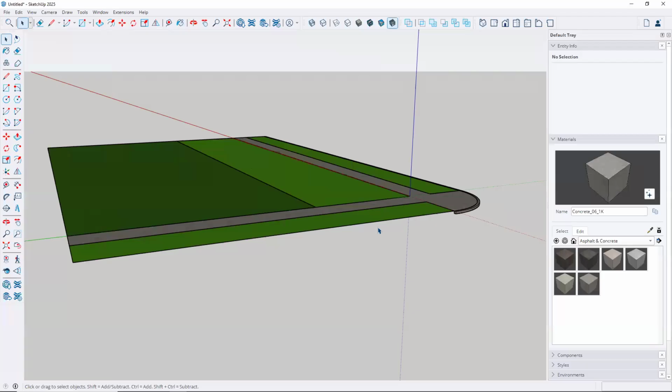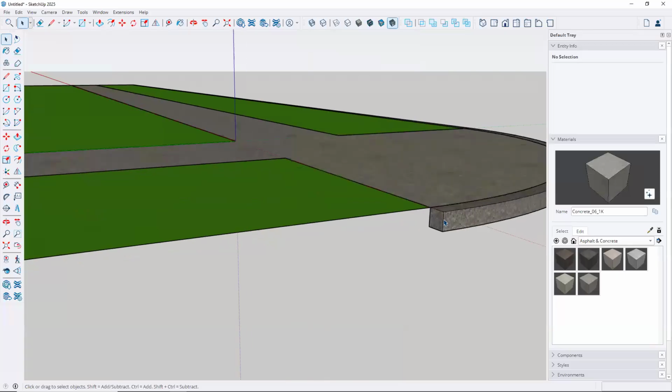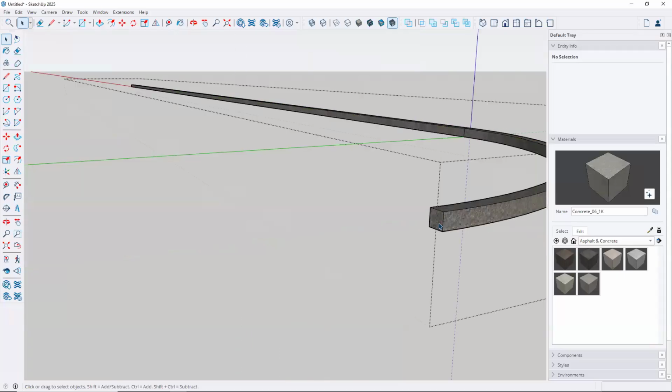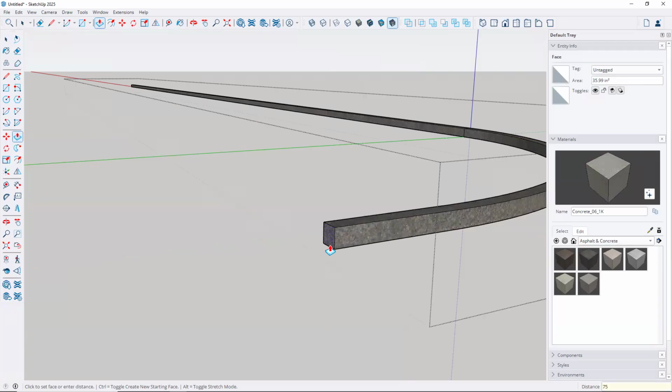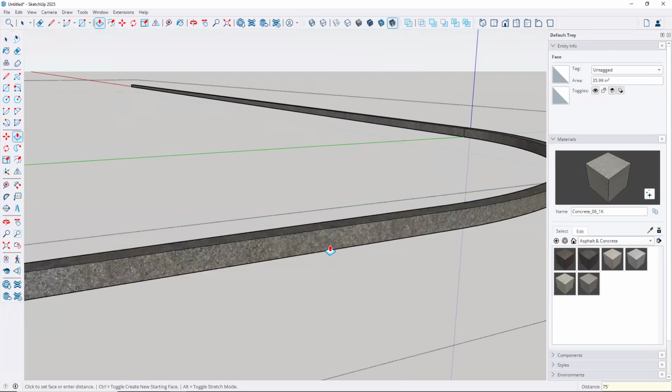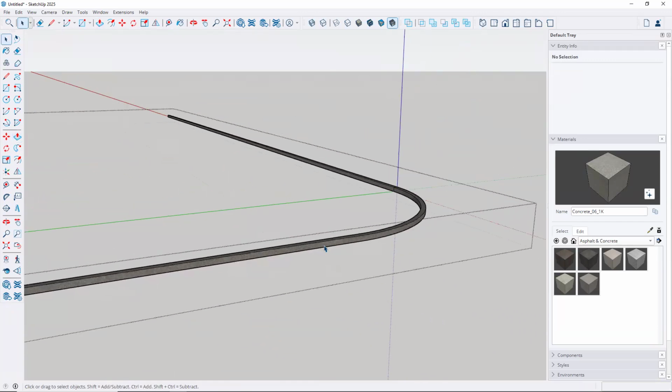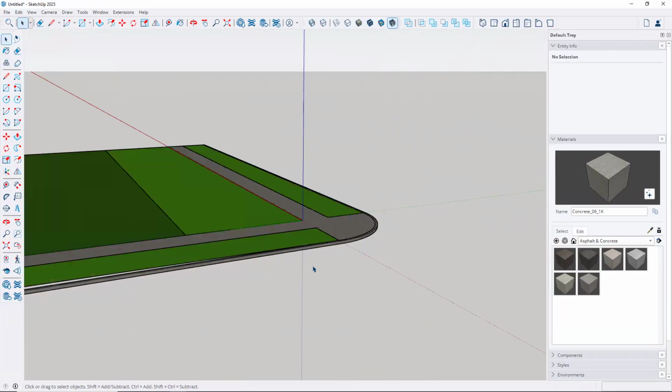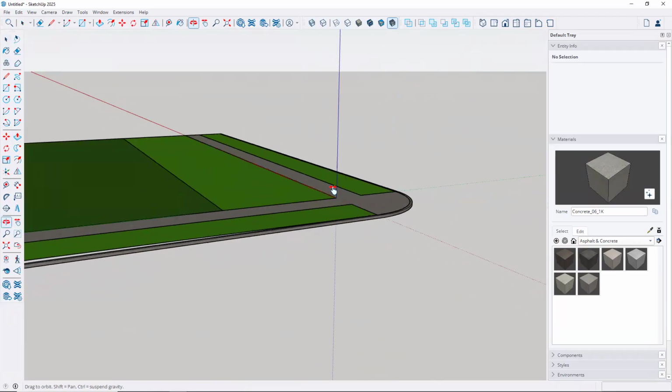All right. So see, I could extrude all the way out there. And I know that the distance is 25 plus 50, so 75 feet. So let me just come in here, give it a double click. P for push pull, click on it here, move it in this direction. I'll type in 75 feet, enter, tap the space bar, zoom out, click off of the object, and notice what it did.